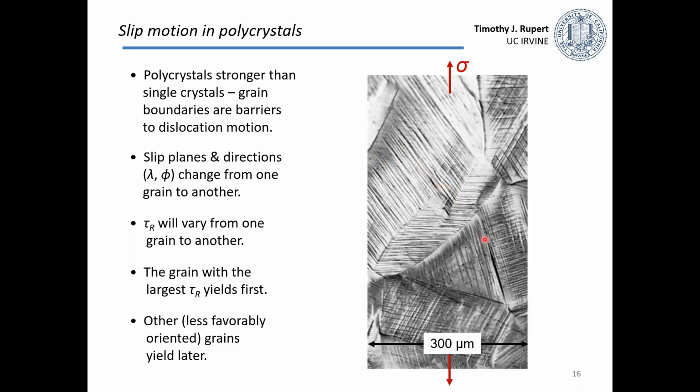And if you look at these different crystals, you'll see that those lines on the surface are oriented in different ways in comparison to how we're looking at it. All that means is that each of these is still going to be that closest packed plane and closest packed direction, but how that's oriented with respect to our viewing direction is different.